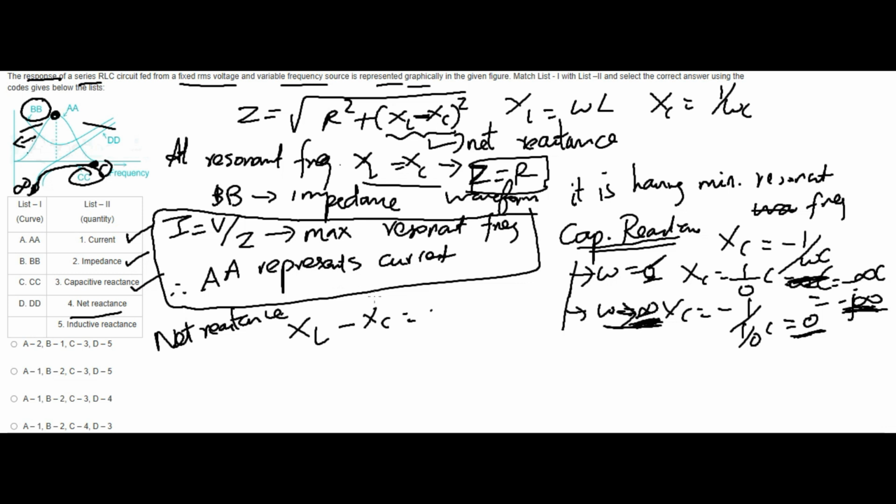So jωL, you use j also, and down is j also, no problem. Minus 1 divided by ωC. If you don't add j also, but if j is added, no problem. I'm just telling about the value of omega equal to 0. If omega equals 0, this term becomes 0, right? And this term becomes minus j times 1 by 0, which is infinite. Capacitive reactance becomes infinite.